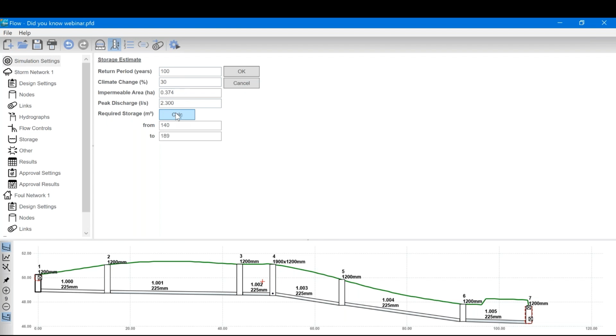So we're going to be adding in for the 100 year, but for the 1 year flow control flow rates, and so this will give us a bandwidth. If it's very free-flowing soil and you're able to infiltrate very well, and you've got a really efficient flow control, which the Hydro-Slide is, it'll be down near the 140. Or if it's very clay and a very inefficient flow control, then it'll be up near the 189 size.